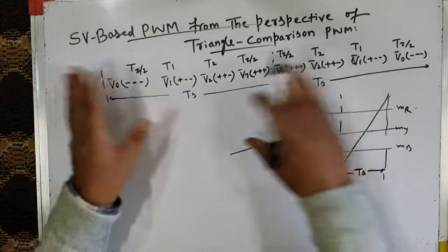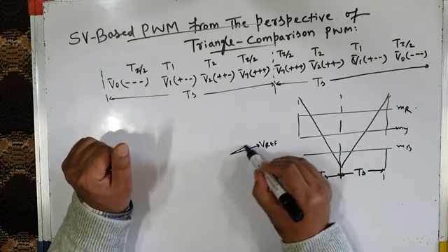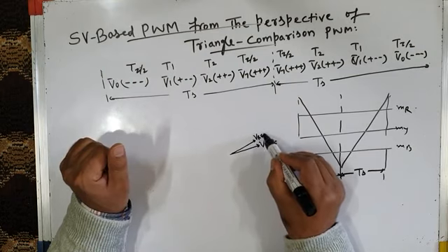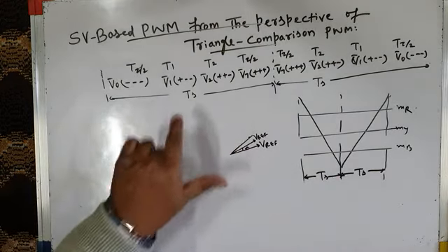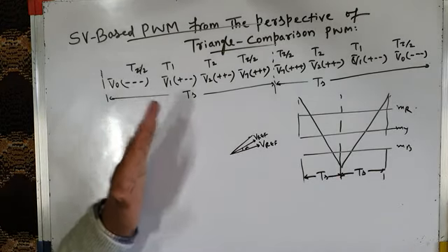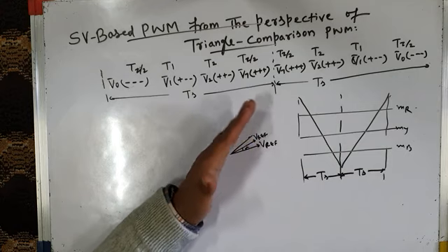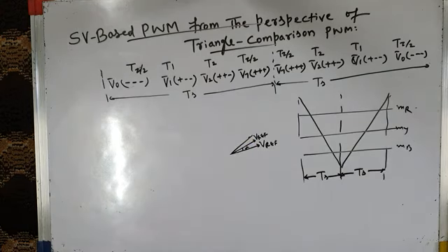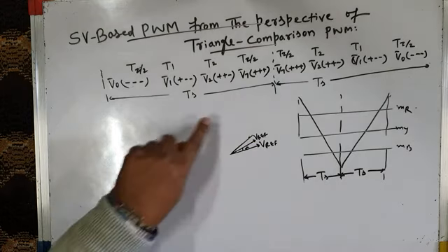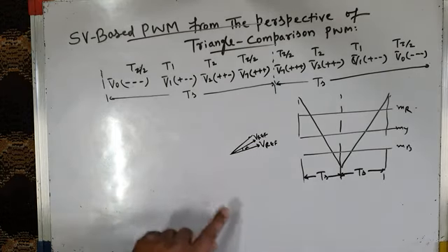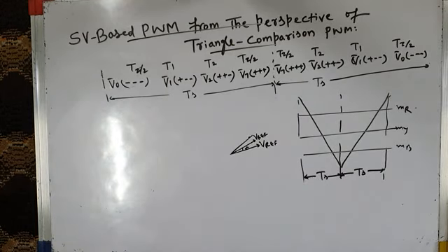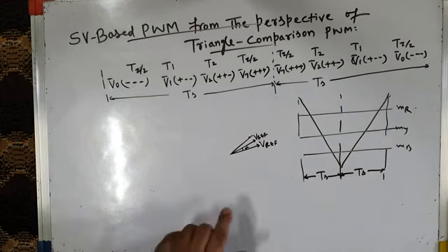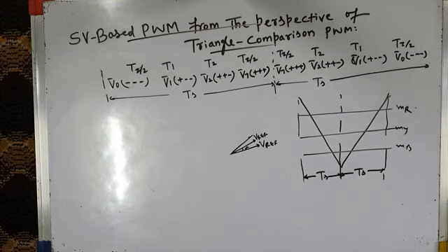In the next sample time, it repeats the same switching sequence, and the reference vector has rotated by an angle alpha, and so on. Depending upon the switching frequency, you will have a large number of samples, and hence a rotating reference vector is created. This rotating reference vector represents these switching sequences, and of course a set of three-phase sinusoidal phase voltages and a set of three-phase sinusoidal line voltages.